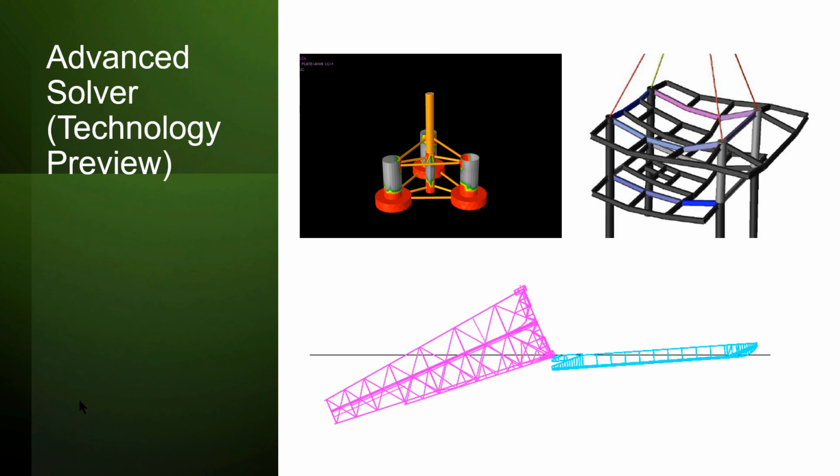The next update is about the structural solver. As we know, for structural analysis, structures should be fixed in space to prevent rigid body motion. This is a basic and fundamental assumption for structural analysis. However, what if we have to analyze structures moving in space or that are not fixed? In this kind of case, we usually apply soft and fake springs to the structures to make the analysis run.